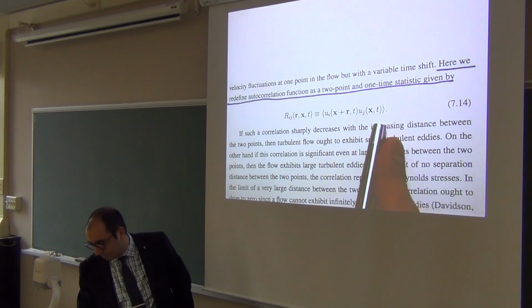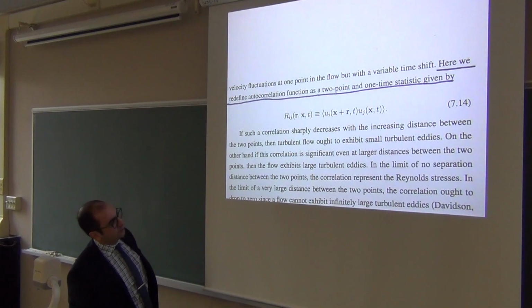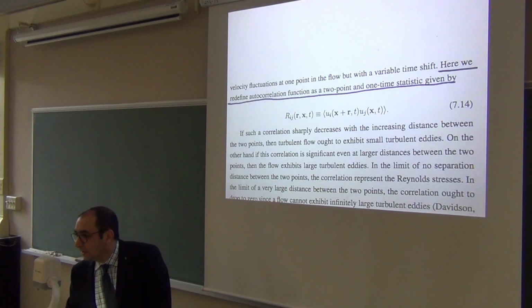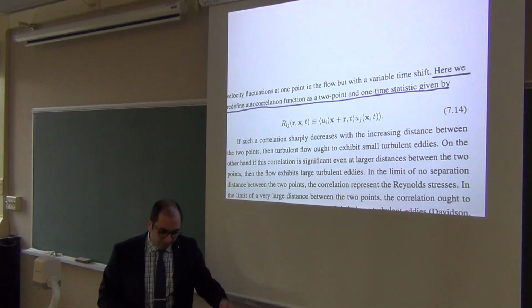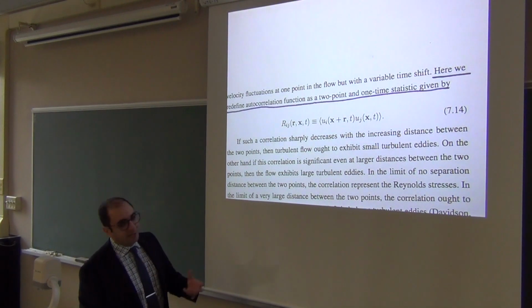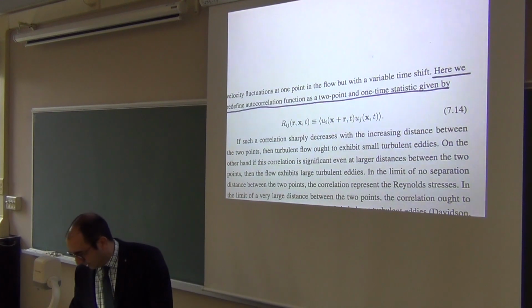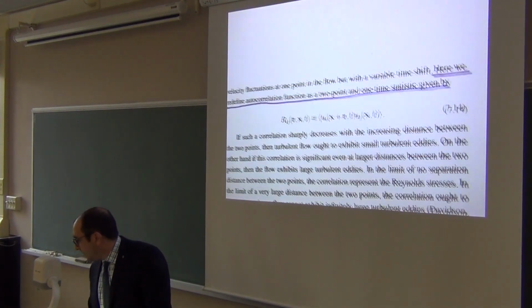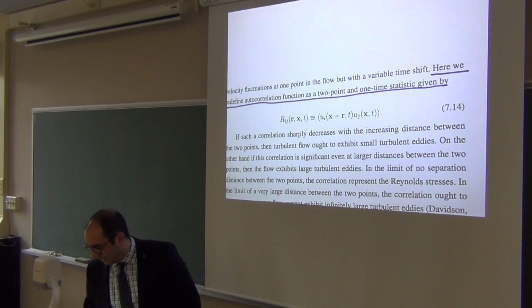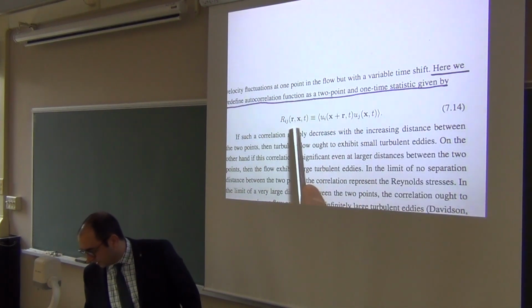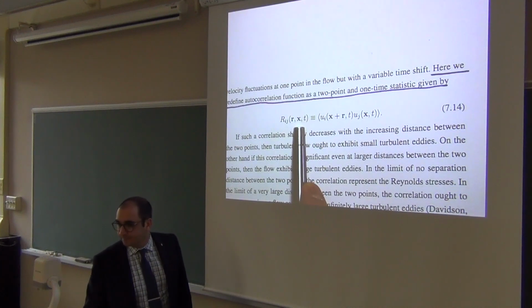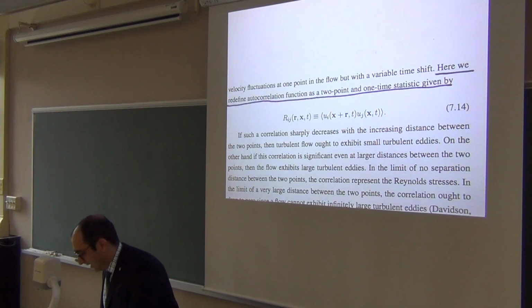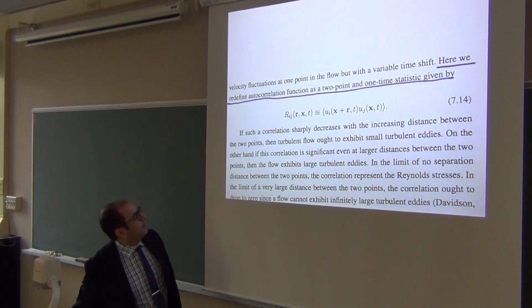Of course, I have time here too, because not all flows are statistically stationary. You could get transient flows, so say if the day repeats, you might do this at any second of the day, if you're interested, for infinite number of days. So as you see, the 2-point and one-time statistic takes a lot more arguments than the autocorrelation. So it can be a little more demanding.